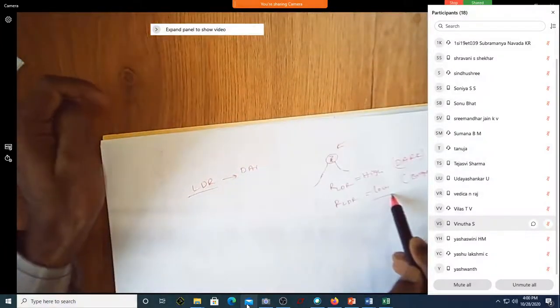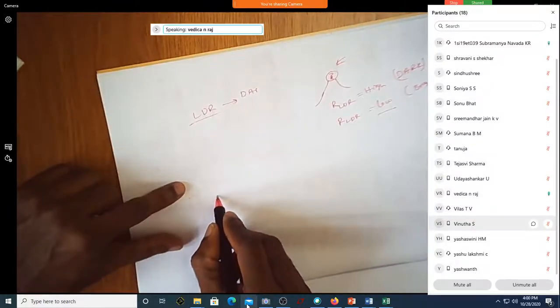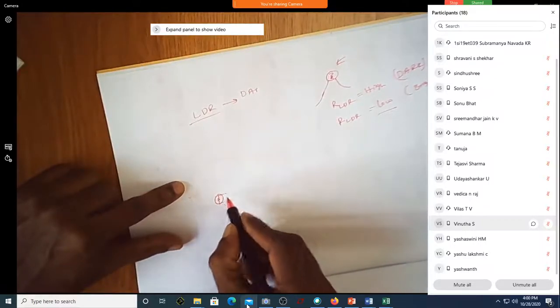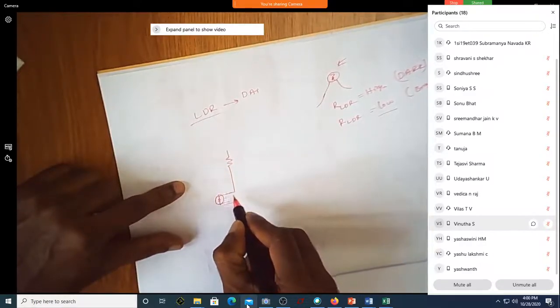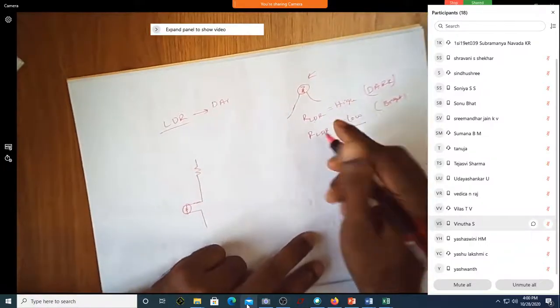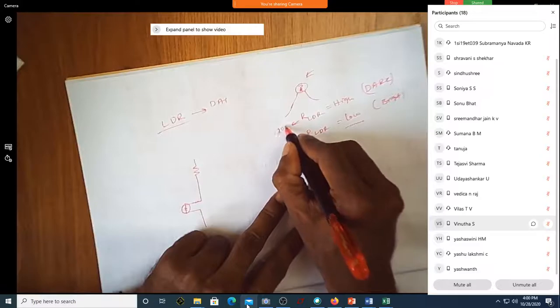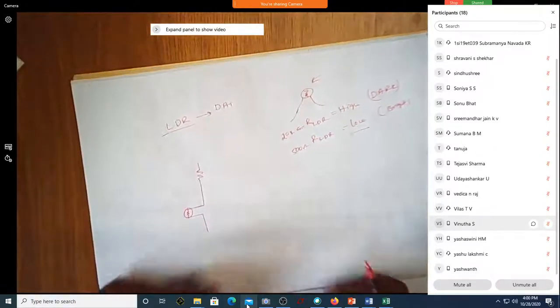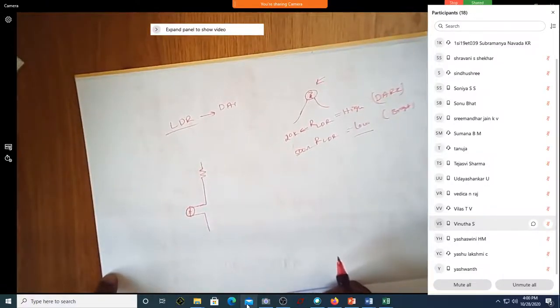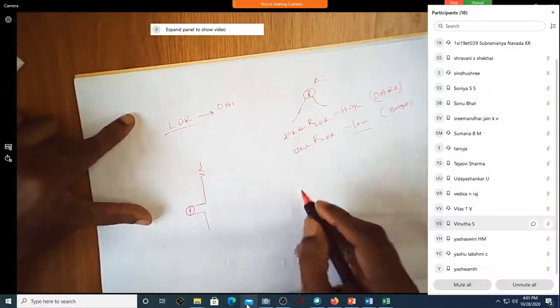Correct? What I'll do is use this LDR here, which has 2 terminals. I will use one more resistor. I am going to measure this resistance. When it is high, assume that it is around 20K. When it is low, assume that it is 500 ohm. I have actually measured it using a multimeter.